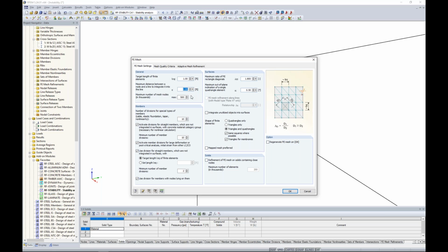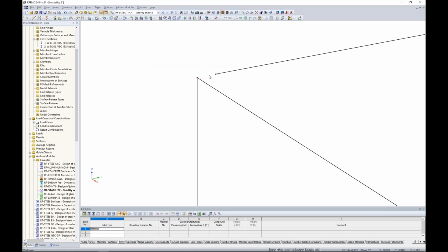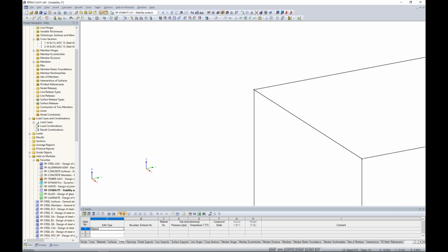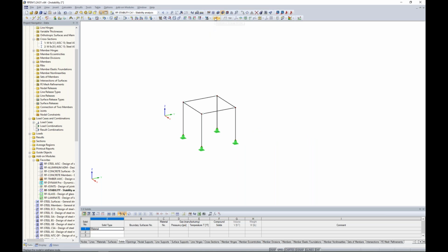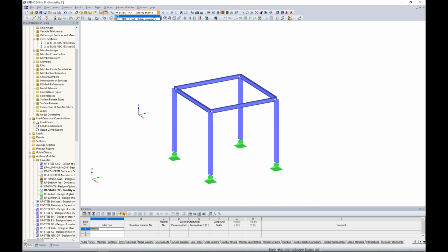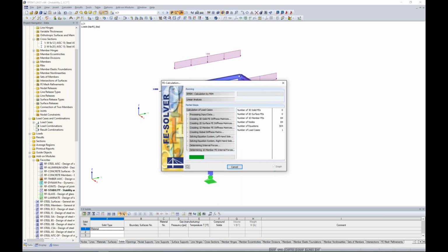Because if you set this to something too big, you're going to begin to merge nodes together during the calculation that really aren't meant to be merged. So we'll leave this as default because clearly this distance is much greater than 0.003 feet, and all we need to do here is just grab this node and snap it to that column. Okay, so hopefully we've alleviated this instability. What we would do now is jump back to load case 1, remember with those same applied loads, and we'll begin to run the calculation.